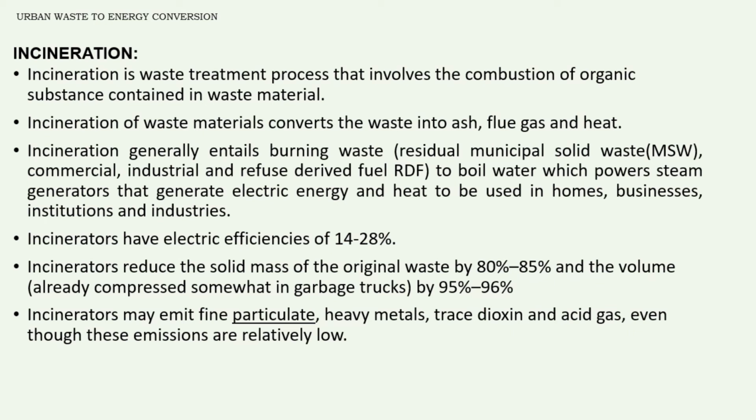Incinerators have an electric efficiency of about 14 to 28 percent. They reduce the solid mass of the original waste by 80 to 85%, and by volume by 95 to 96%. They also emit fine particulate matter, heavy metals, traces of dioxin, and acid gas, even though these emissions are relatively low. So this is about the incineration method.